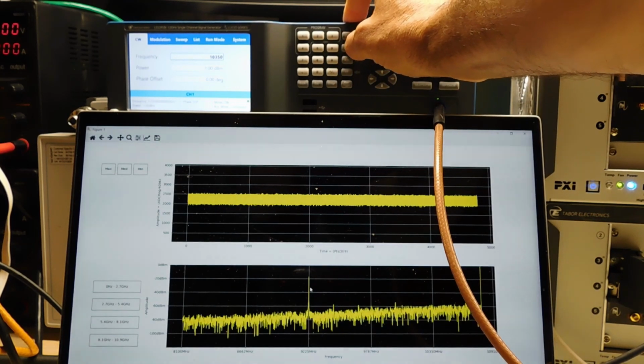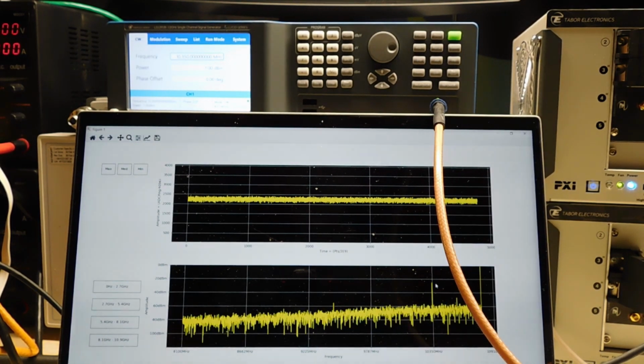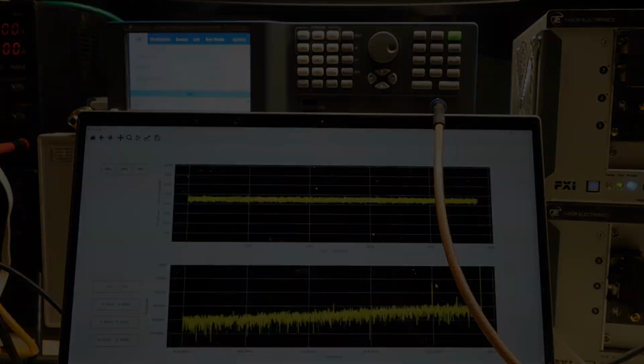10,350 megahertz. So that's 10 gigahertz. So you've got a signal here, and you can see the roll-off is a lot more prominent, but we are digitizing a signal at greater than 10 gigahertz with a sample rate of 5.4 gigasamples per second. So this is one of the many ways that you can use multiple Nyquist zones to digitize signals higher than the first Nyquist zone, which would be 2.7 gigahertz, because our clock is 5.4 gigasamples per second.